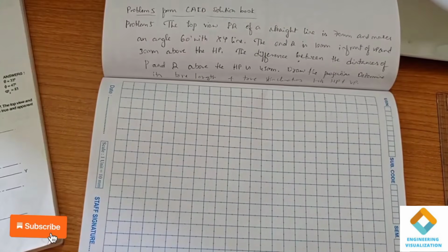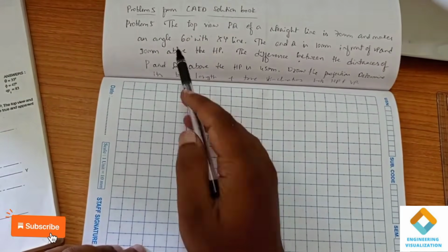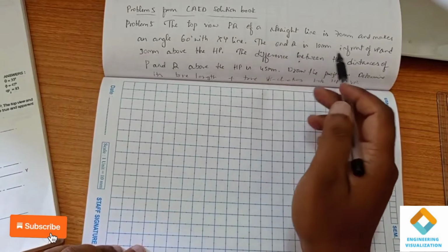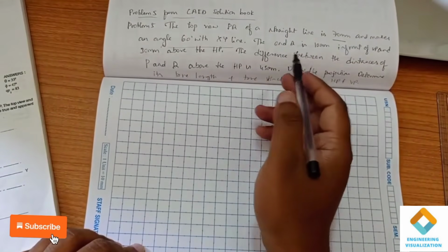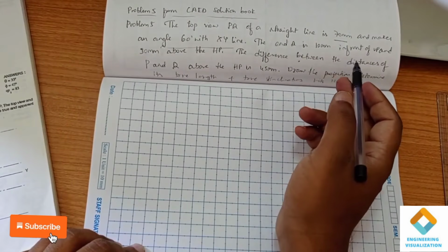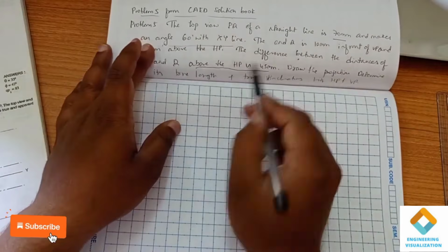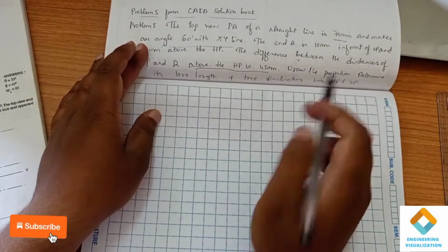We solve another problem from the CAD solution book, that is problem number 5. Okay, so what is given in the question? The top view PQ of a straight line is 70 mm, and it makes an angle of 60 degree with XY. The end Q is 10 mm in front of VP and 30 mm above HP. The difference between the distances of P and Q above the HP is 45. So draw the projections and determine its true length and true inclination with HP.